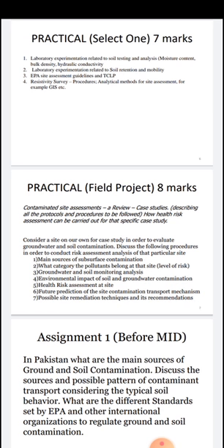And then another issue with a landfill can be the settlement of soil due to overloading at the ground surface. In most cases, once we close a landfill, it is normally opened to the public after taking some remedial measures, and once it is open to the public, it is directly under the influence of extra load, which can leave some negative impact. So very strict monitoring of the landfill is required every time, even after its closure.